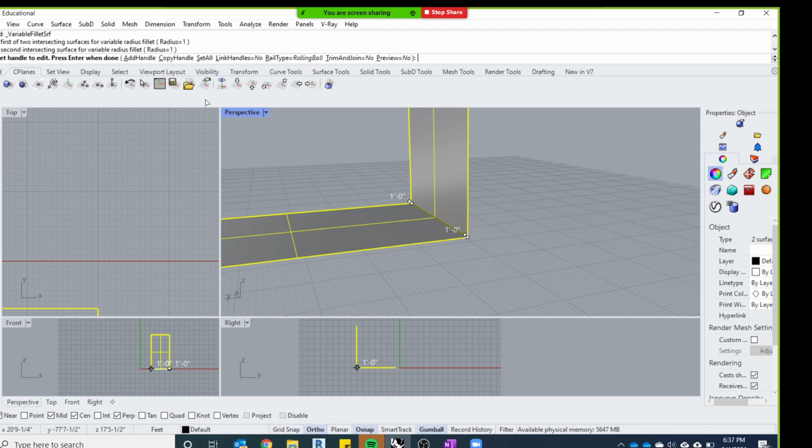creates that fillet. And if you forget to trim it like I did, you can use the trim command. So I just typed trim, choose the cutting object, trim that, and create a more unique fillet, right?